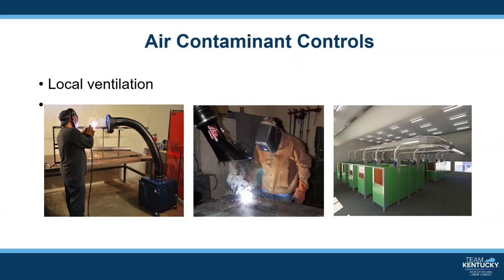For example, when the portable extractor has a 10-inch wide hood opening, the sweet spot should be approximately 10 inches from the arc source, while being angled away from the welder. Slight adjustments may be needed, but 10 inches distance should be a good and effective starting point. The photo demonstrates the proper hood position that is both effective and non-obtrusive.